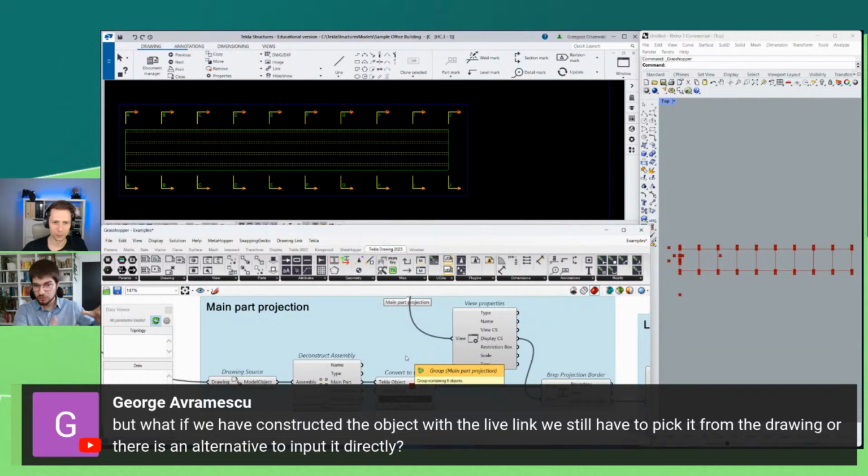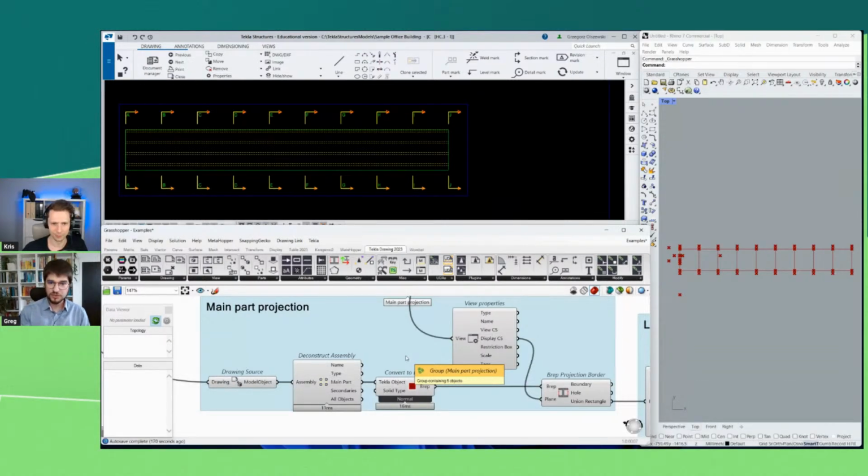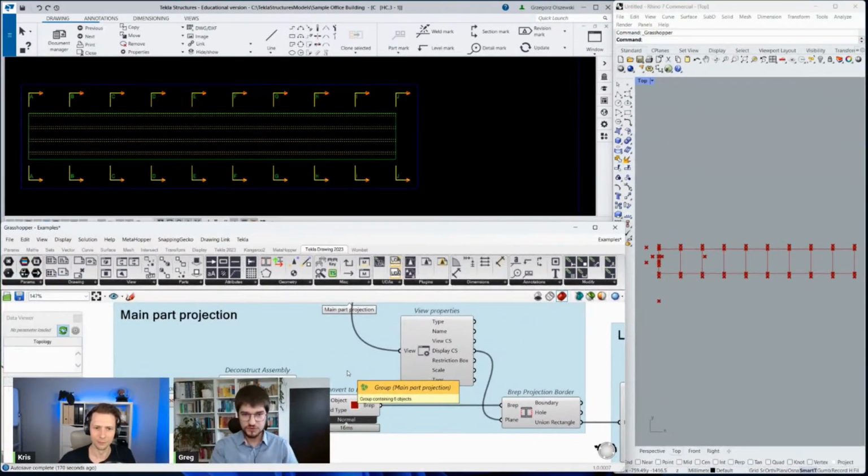So if it is incorporated into the Tekla component, the standard one, or with a component from Grasshopper, it doesn't matter. And it doesn't have to be baked in Tekla from Grasshopper. It can be from the live link element, and the connection with the live link doesn't have to be broken. It's just an element, so it will be visible anyway, right? Yes, but to enter the drawing, for the assembly drawings, cast unit or single part, you need to have those objects in the model. They have to be numbered.